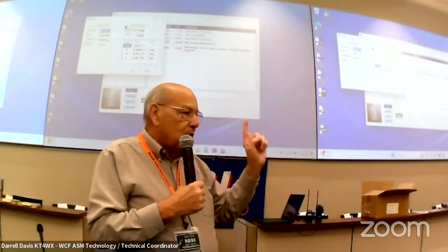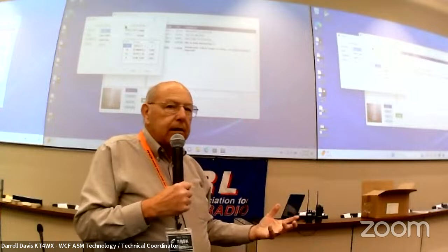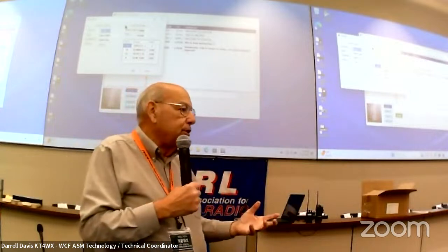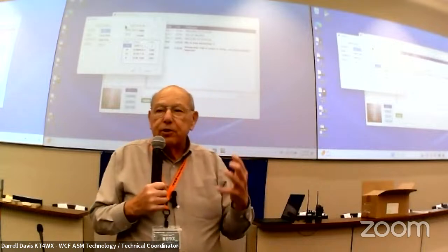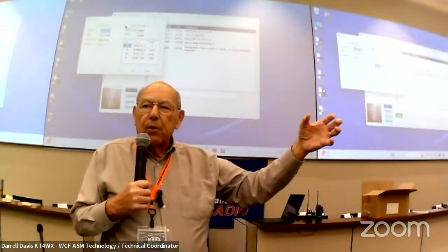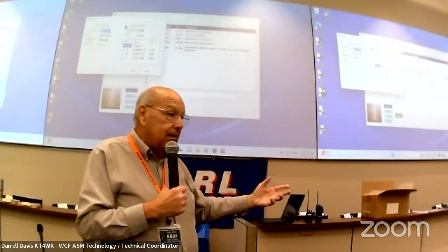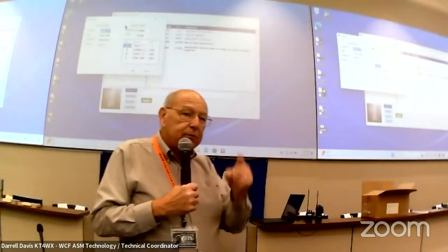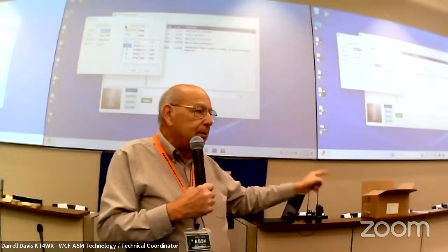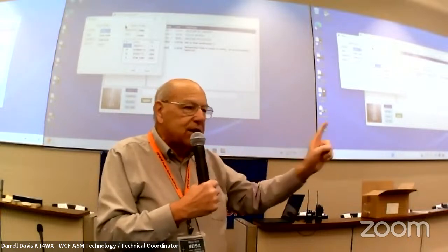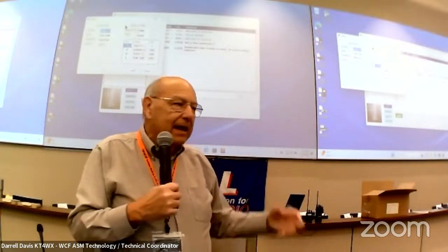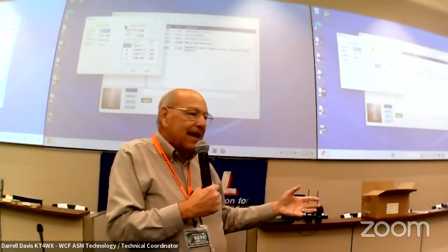If all you have is the one ID, it's not a bad thing, but just remember too, and this is one of the things we didn't mention this morning, if you've got a portable radio and the ID is 12345, and you've got a mobile radio with the same ID, your wife will never hear you when you're using the portable because the 2 radios with the same ID can't talk with each other and they can't hear each other. It's kind of like 2 computers with the same IP address. They don't work well, but they'll still work talking with everybody else.